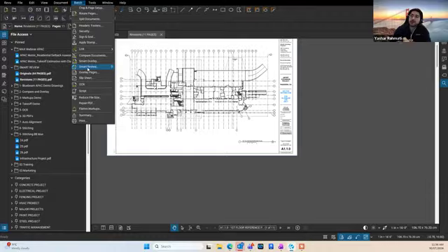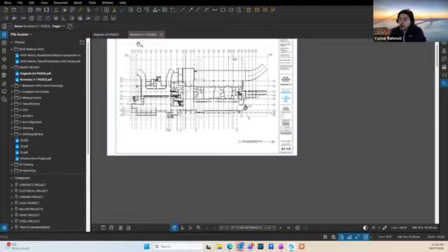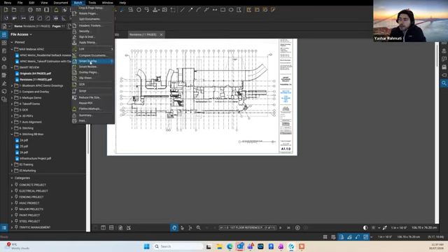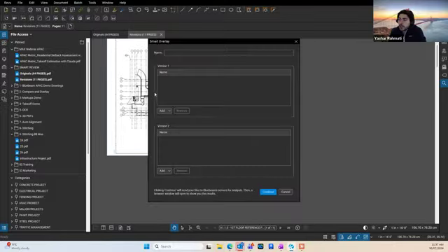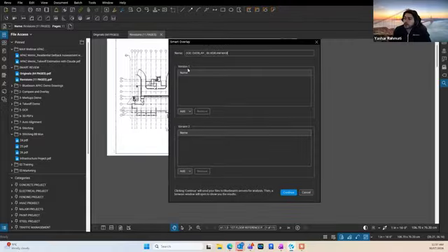Also, it gives us a very interactive dashboard, from which we can clearly see how much change we have had in different sets. So let's run that and explore that area. I don't need to spend time finding the corresponding pages from one version to another. All I need to do is jump into my batch, jump into Smart Overlay, and define a name for that. For example, I'll call it document review or document overlay, and then, for example, Bluebeam Max. And then what I need to do is select my version 1.